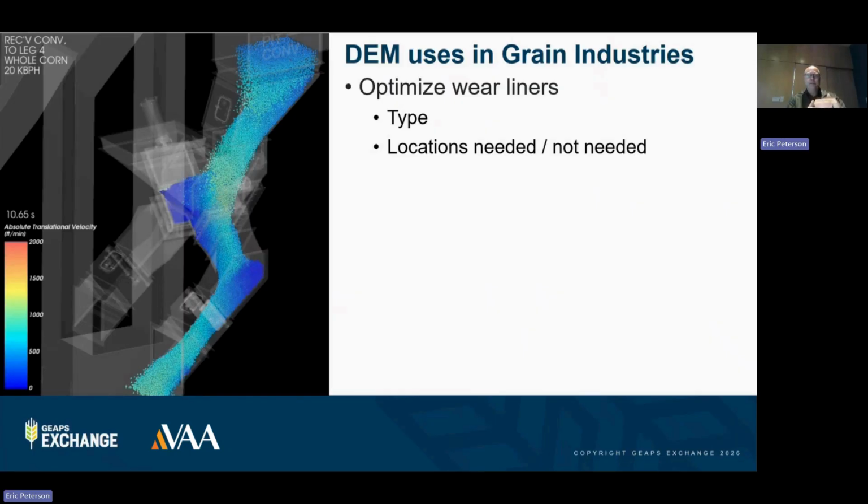And as you continue to speed up, it cuts down and down and down. And on a long rectangular spout, maybe it's a 30-inch tall spout, there may be only 2 or 3 inches of grain sitting in the bottom of that spout, speeding down before it hits an elbow. So there's a lot of wasted structural steel and wasted plate steel and chute work that could be optimized.